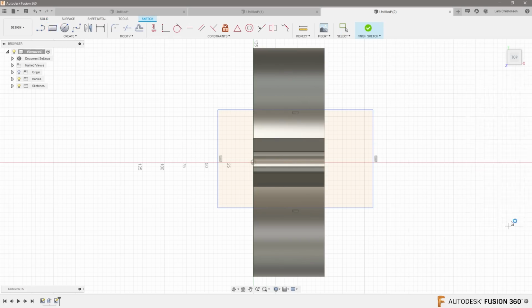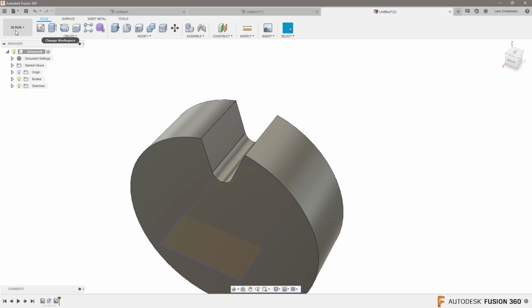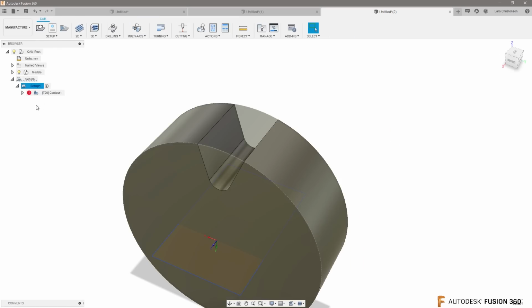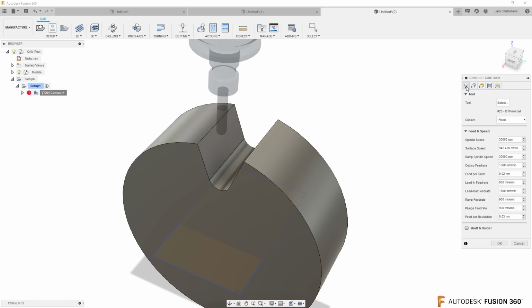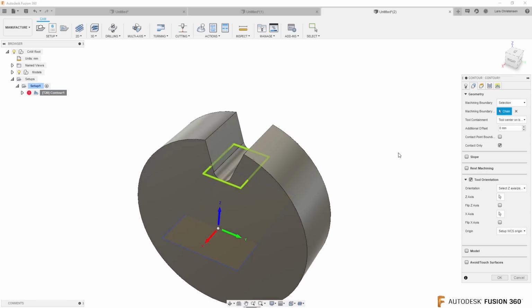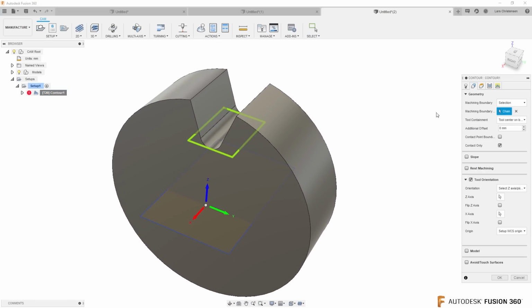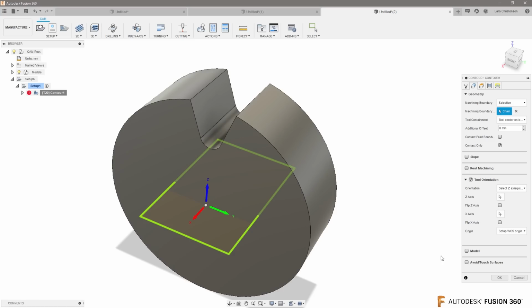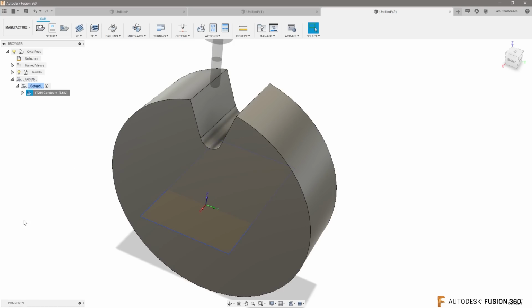Of course, you should fully define them, but you can select those as your boundaries inside of the 3D workspace. So you saw how I before hit selection and I got this specific chain from the model. But if I exit out of that, you can actually also select the 2D sketch. And now it will use that as its boundaries.